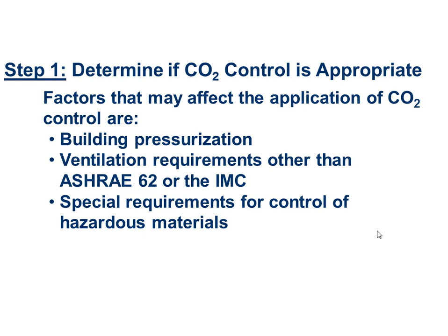And the exhaust system for many facilities is just a function of adding up all the total exhaust bathroom fans. If they add up to be 1,000 CFM, I don't want to cut my ventilation air from 3,000 down to 0. I want to make sure it stays above 1,000 to make up the bathroom exhaust. I've got to think about any ventilation needs that are being driven by non-people sources, right? So if I've got any chemicals or weird things going on in the building, like a laboratory, this is not going to be a good idea to use CO2 sensors. CO2 sensors are for ventilation needs that are driven by the amount of people that are there,